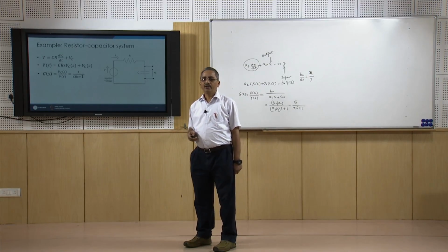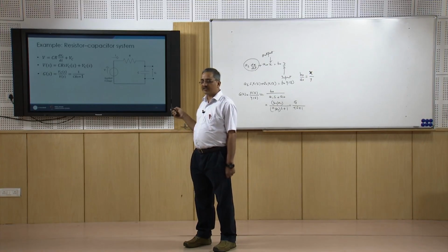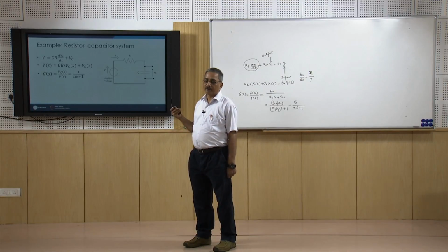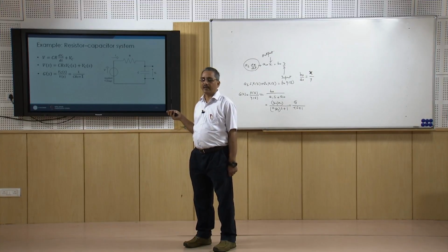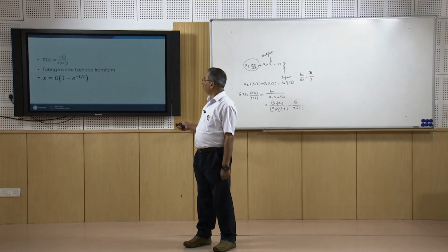And the use of this transfer function is that by measuring the output as a function of time, for the given transfer function and input, we can do this for any first order system, say a hydraulic system or a thermocouple, and work out the time response as we have seen in the previous case.